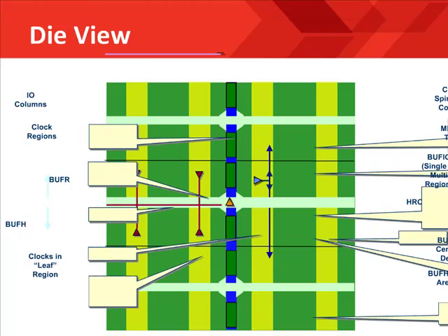the control signals associated with the neighboring clock region. This behavior of isolating the MMCMs, a single clock region, with a fixed number of CLBs and a fixed number of I/O pins, and a single I/O bank, is reflective of an ASMBL architecture. This is a characteristic Xilinx has used with Virtex-6 device families and basically implies that as the density of the FPGA increases, you basically get a fixed number of additional regions as the density grows.